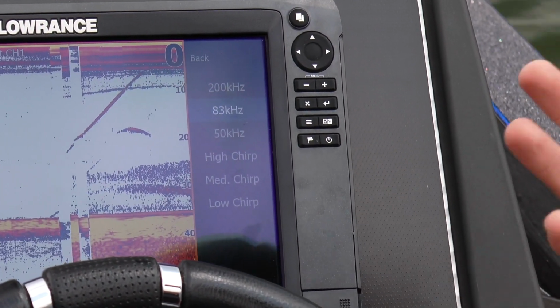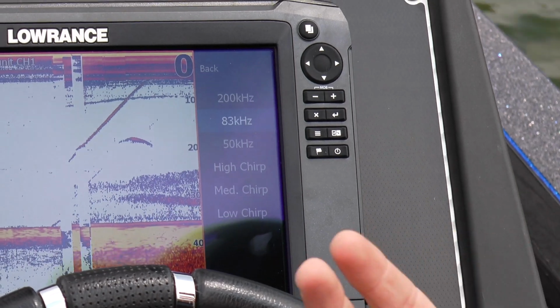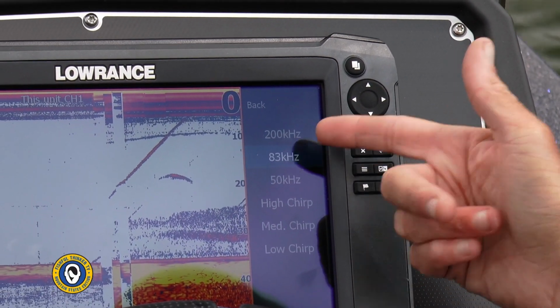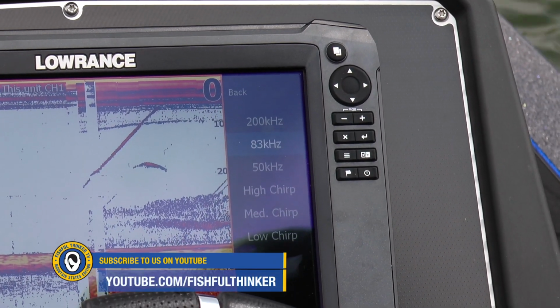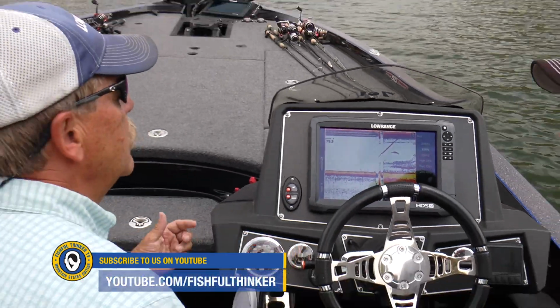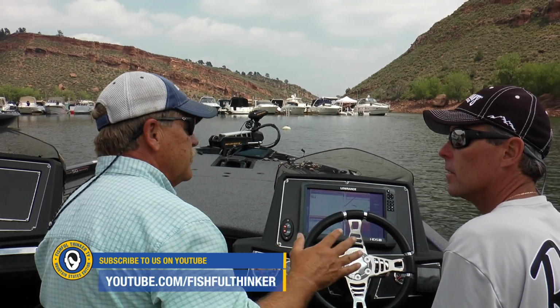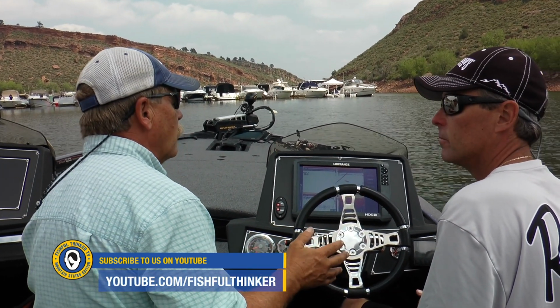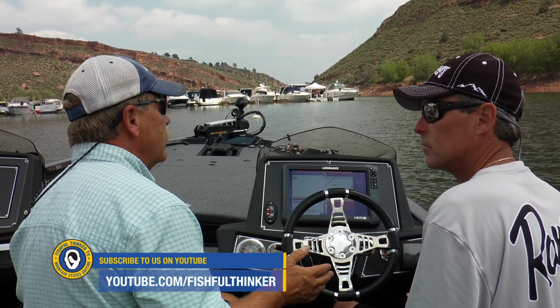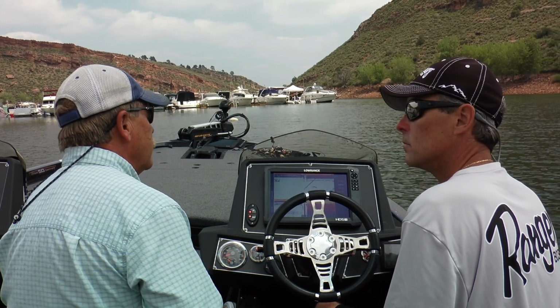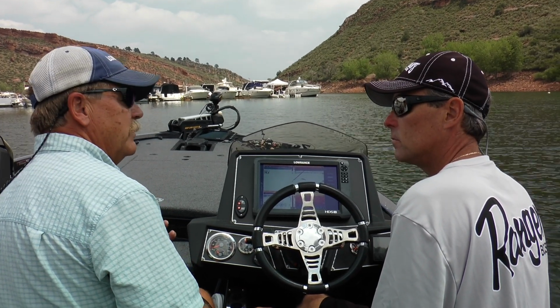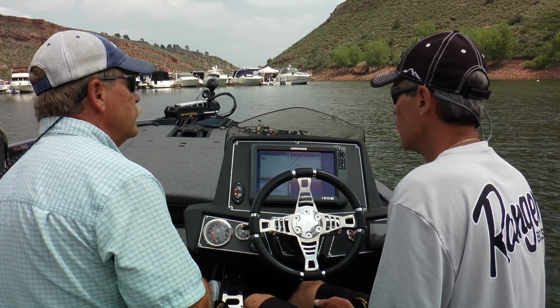A higher frequency, we've already talked a little bit on the show before you got in the boat, is more detail. What do I gain by going to an 83 kilohertz? 83 is going to give me a little wider signal, and so if I'm in fairly shallow water, I'm going to be able to see more to the side of the boat. Okay. I'll pick up more objects. The cone is going to be a little wider, so I'll be able to see more things. But what I don't see with 83 is I lose some of that resolution that you see with 200.